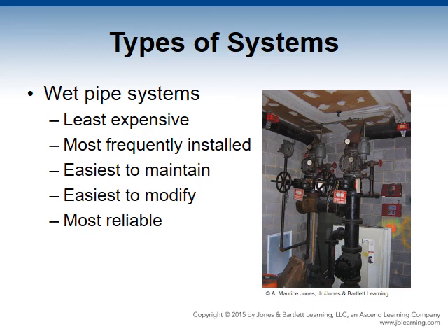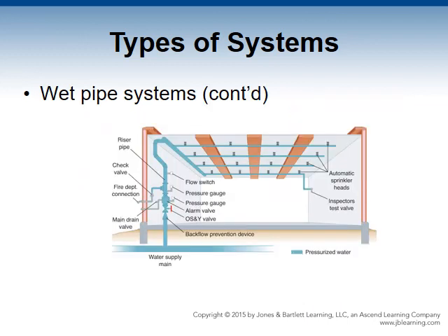They require a dedicated and automatic water supply. They are common in almost every type of building and usually have some of the following type components: an alarm check valve or other flow detection alarm device, which are used to provide an alarm and function to notify the water is flowing, and to act as a check valve to hold pressure in the system and not allow the fire sprinkler water to flow back into the potable water supply.